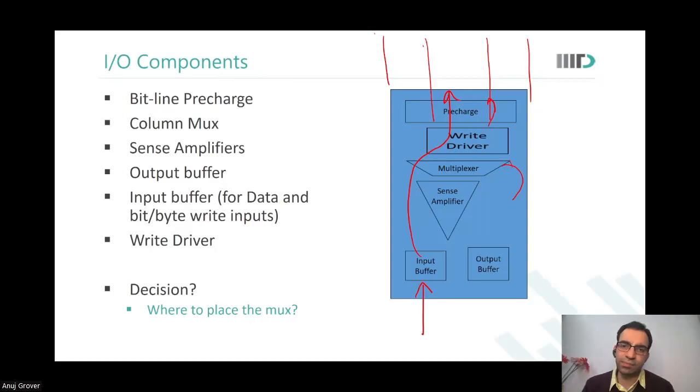Okay, let us say memory write time will not change. What will change? The time it takes to discharge the bit line to 0 has changed. That you agree? Yes, sir. That needs to happen before the word line arrives. Yes, sir. So if the word line is a clock, then what would this race condition be called typically? If you have a flip-flop, it has a clock as an input, and you say that data should arrive this much before the clock arrives. So setup condition, setup right.